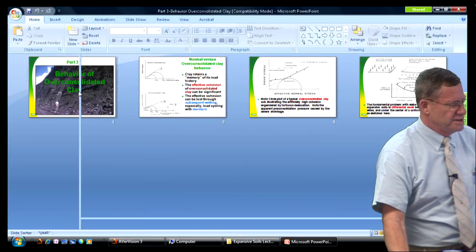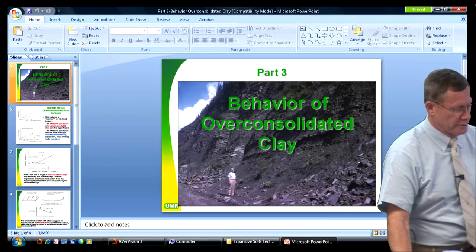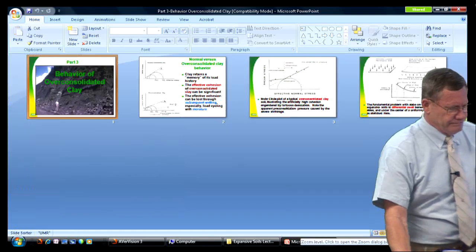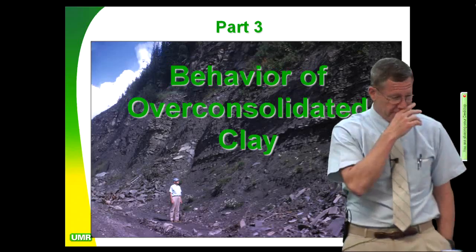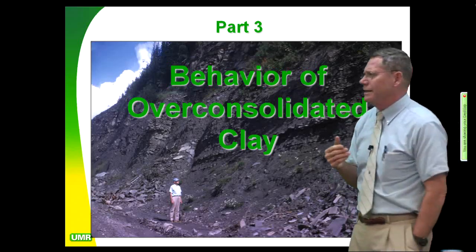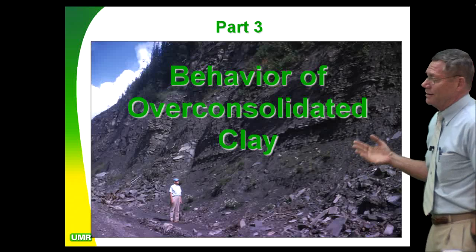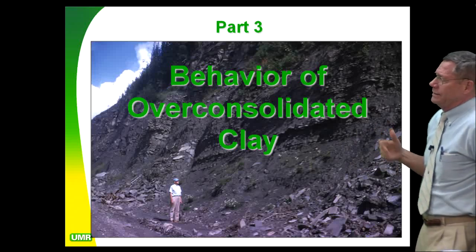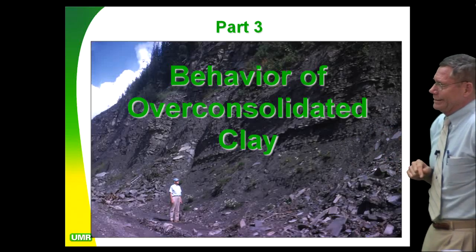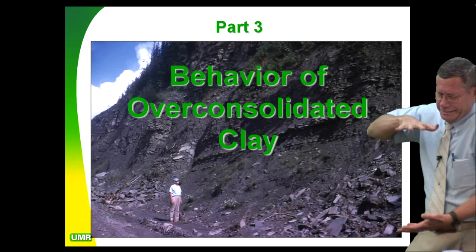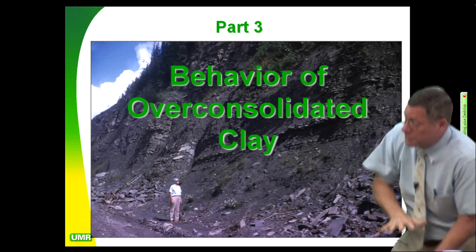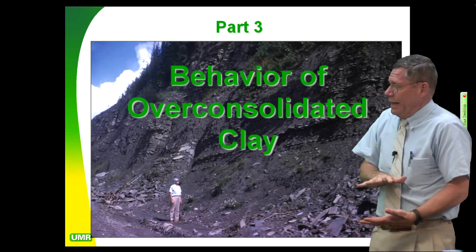Part 3. Part 3 is not real long, but it's real important. The biggest problems I've had in my practice have all been overconsolidated clays. I could teach a whole class called The Perils of Overconsolidated Clay. Why? The shales. Shales have been compressed tectonically. They've been taken down way in the bowels of the earth. And clay has a memory.